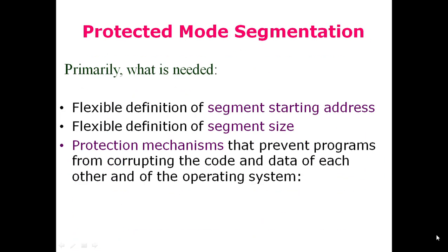Now, protected mode of segmentation. There are some problems with the real mode of segmentation. Primarily, we needed flexible definition of segment starting address. In real mode, segments can be defined at some set of addresses, but not at every address of the memory. So we need flexible definition of segment starting address.